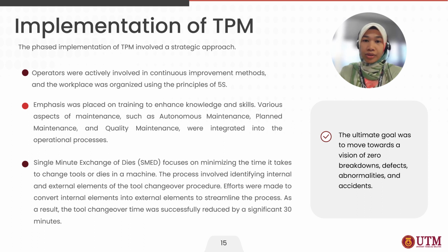The phased assimilation of TPM is characterized by an imperative emphasis on continuous improvement methodologies. Operators, integrated through this process, engage in a 5S-driven workplace organization while receiving targeted training for skill elevation. Maintenance facets such as autonomous maintenance, planned maintenance, and quality maintenance are meticulously integrated, aligning with the vision of zero breakdown and defects.